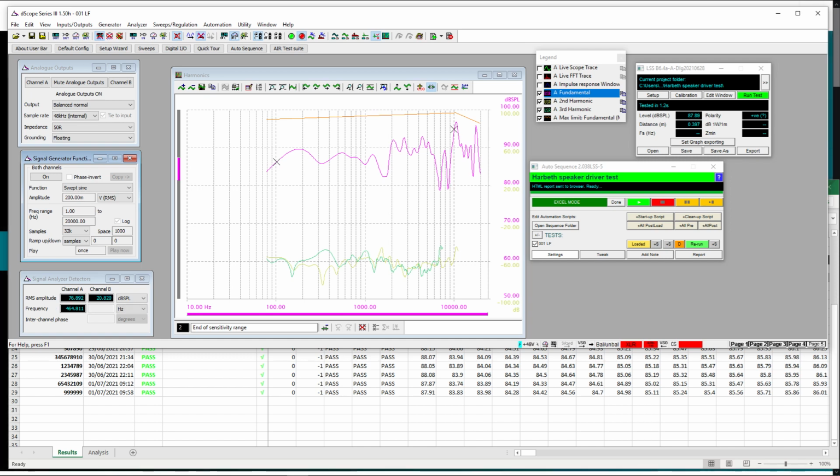The frequency response can be displayed as a relative trace relative to a reference, and so in that way it would give a flat line. If we tested, say, a speaker, saved it as a reference and tested it again, the result would be more or less a flat line, and that makes setting limits much easier. But of course you still have a potential gain offset between the two, particularly if you're testing different speakers.